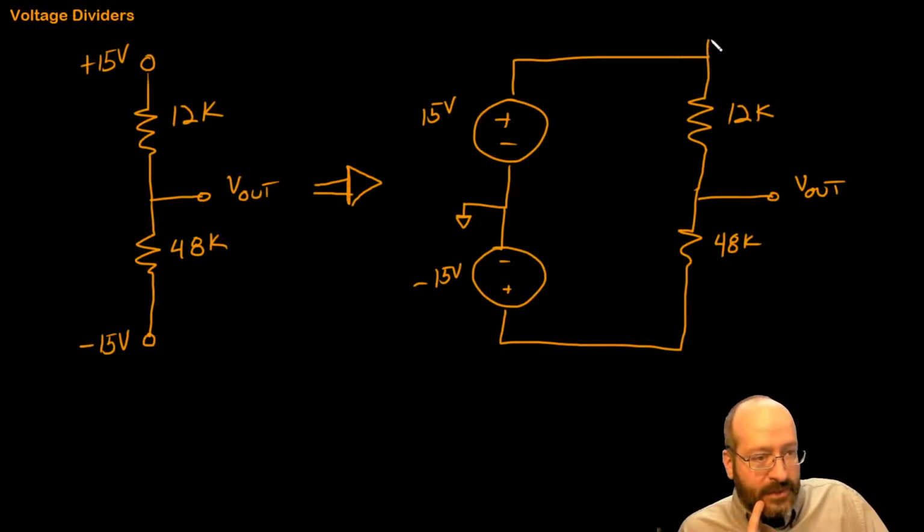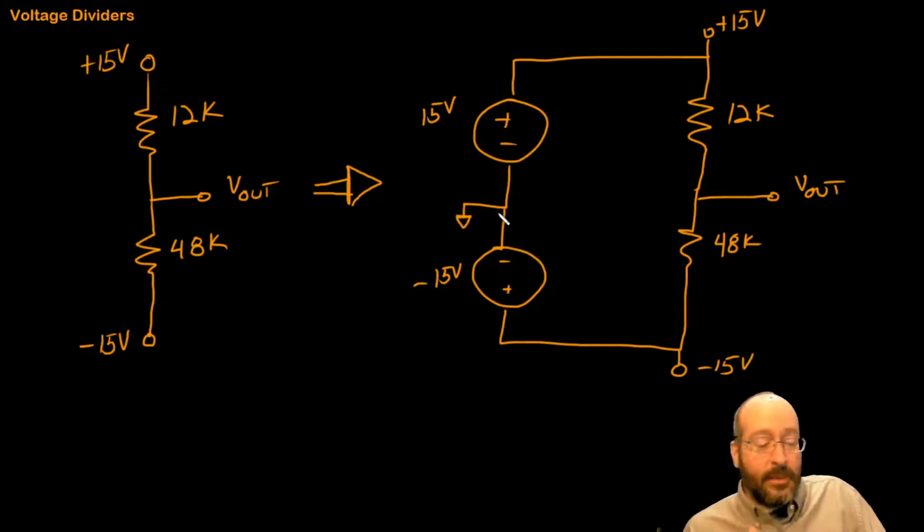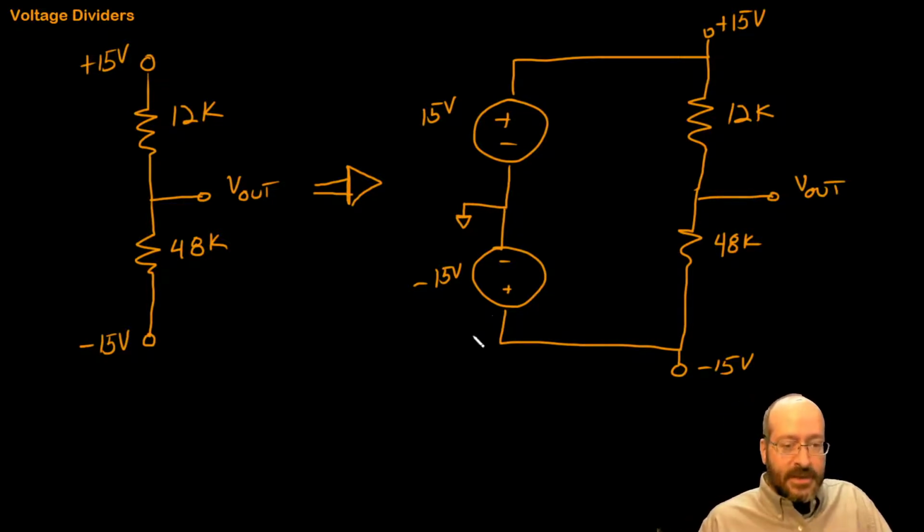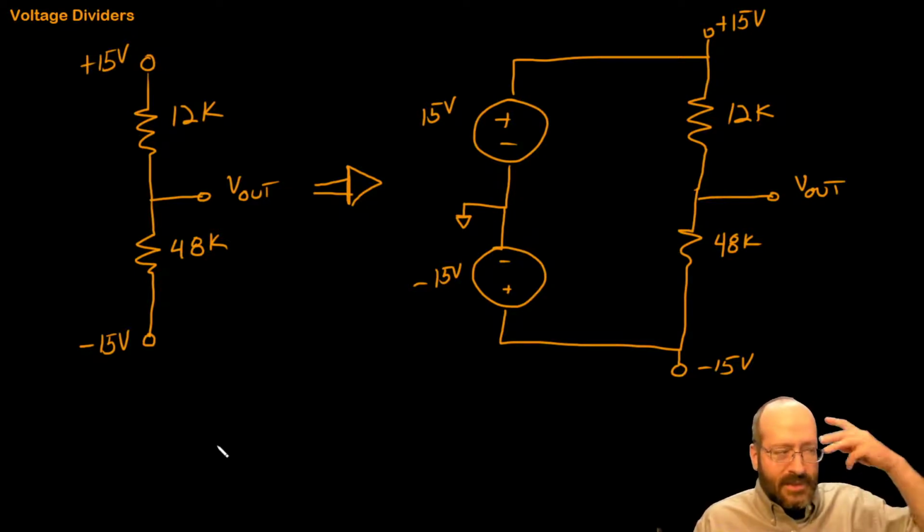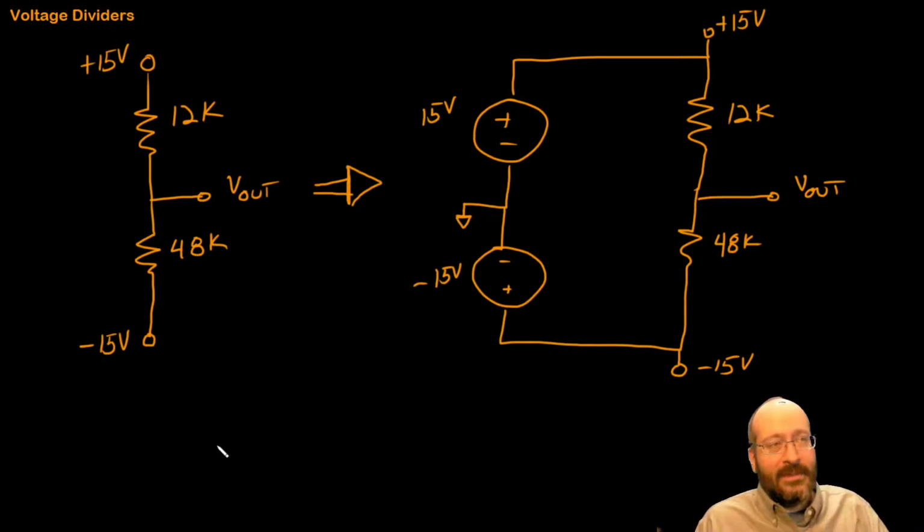Okay. So that the side with the labeled voltage is always on the positive side, and the negative side is always on ground. Okay. And this is negative 15 volts. So if I move from ground, which is 0 volts potential energy, over here, I've gone up, but I've gone up by negative 15. So I end up at negative 15 volts with respect to ground, thanks to that. Okay, so you got to think about these pluses and minuses. The pluses and minuses, you got to find good habits to get it right.